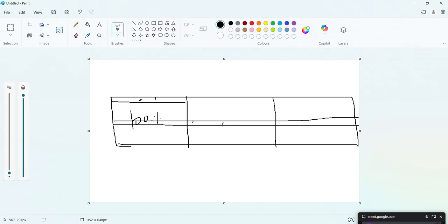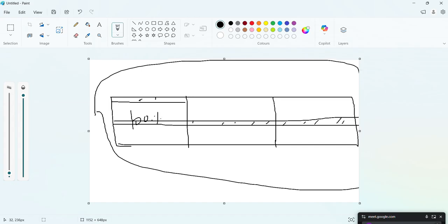So in the SWMM method we have options where we can split this green area from the road, from the impervious area. If you take this whole thing as an impervious area, it will give more runoff. But if you consider this green area in your catchment parameter, the runoff will be less. So we can reduce the pipe size and we can reduce the storage whatever we need. So for the accurate measurement, we'll be using 90 percent as impervious, and the small area will be considered as 10 percent pervious.